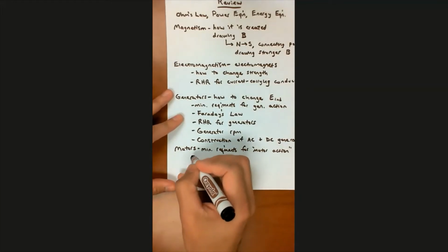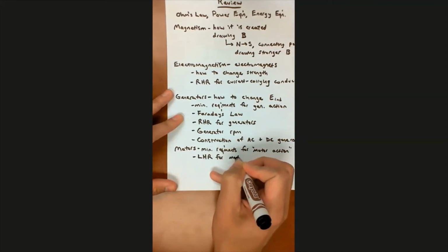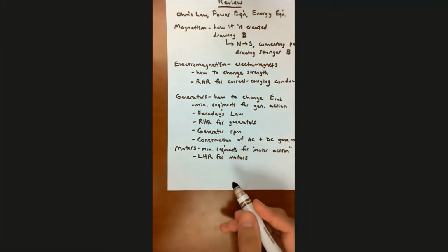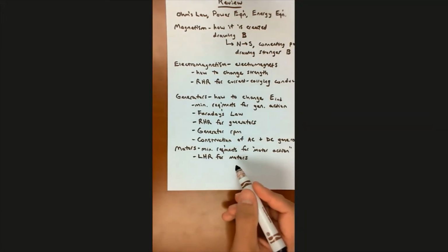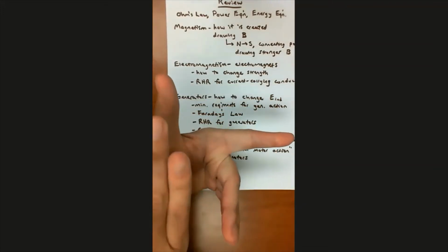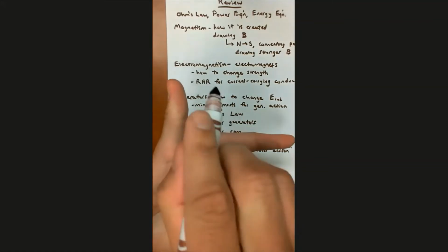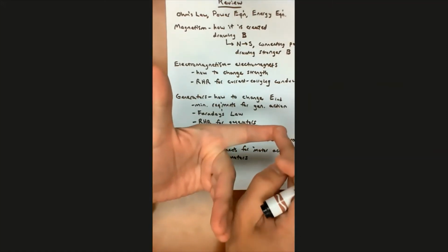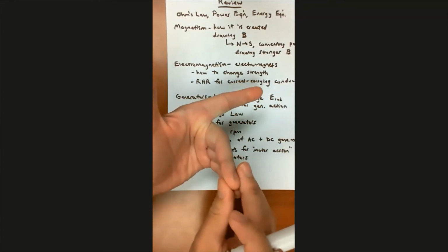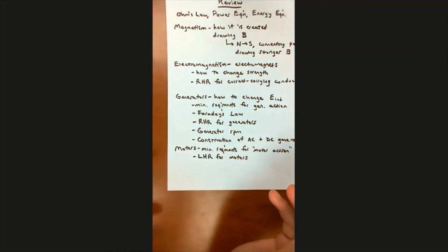We had to apply the left-hand rule for motors in order to determine which direction the motor would rotate, or which direction the applied voltage is, and things like that. And remember, your left-hand rule is very similar to your right-hand rule for generators. Your thumb gives you the direction of the Lorentz force, which is going to cause motion if it's free to rotate. And then your first finger is the direction of the field from north to south, and your second through fourth fingers are the direction of the current flowing through the armature as caused by the applied voltage.